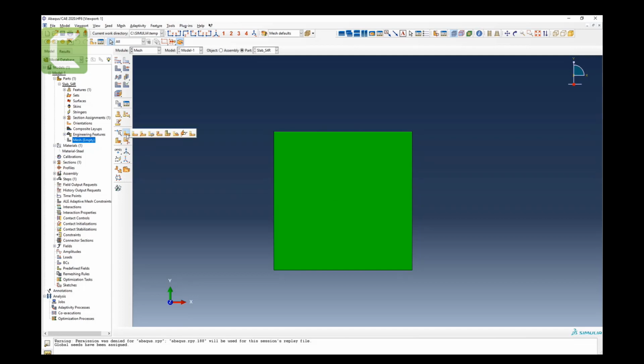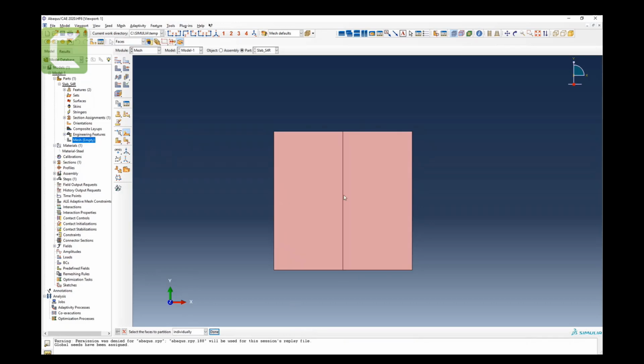We can do it here. These ones, partition cells using part between 2 points. So that's all good. Select the start point. We can do this start point and finish at this point and create partitions. It will create this line where you select your points. Let's create these ones and select the faces for the partitions. Let's select all, done, and we're going to use from this point to this point and create partitions. So you have these partitions.